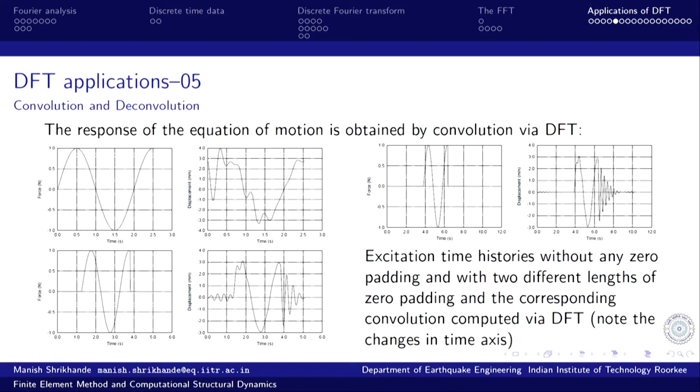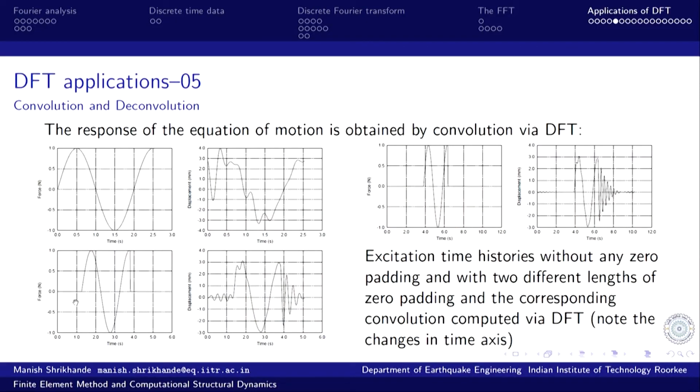So what is happening here? The problem is that when we compute the DFT, it is computing the response of a periodic system to a periodic excitation, with whatever excitation we are looking at repeating itself. The excitation we look at is 2.54 seconds, and then this pattern repeats.